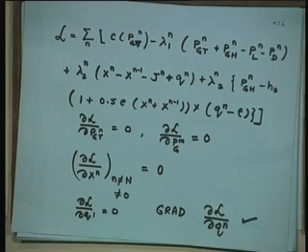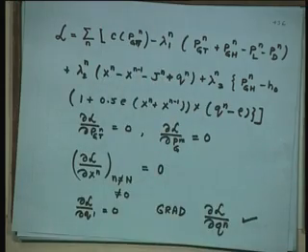If there is a nuclear plant also, well, you can model it like a thermal power plant. Again it is a cost equation, and normally nuclear is used as a base power plant, so it really does not participate in the optimization. What you do, you subtract that nuclear power generation from the load, and the modified load is to be supplied by hydro and thermal. But if you are fussy, if you are very sticky, no, I want optimization, then include it in this cost function here, plus C of PGN, nuclear.